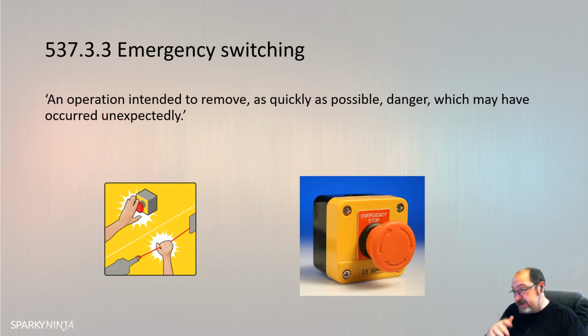A device for emergency switching shall be a device that latches in the off position, unless both means of operation, switching and re-energization, are under control of the same person. The release of an emergency switching device shall not re-energize the relevant part of the installation. Okay.